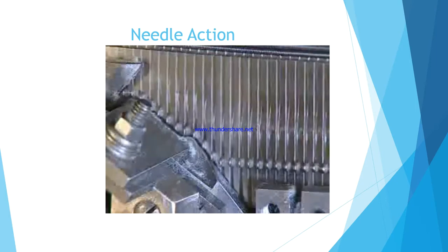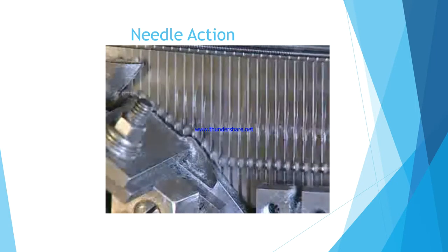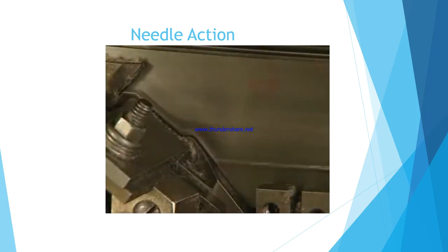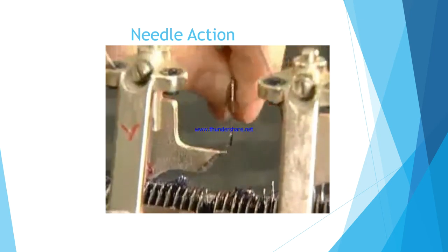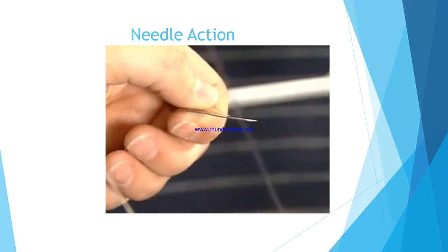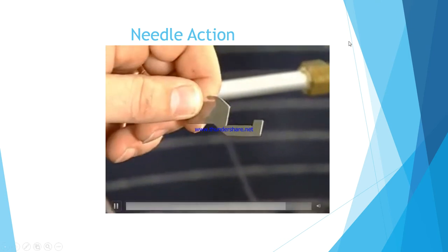And remember that this machine has a cylinder that contains vertical grooves and slots to hold the needles that move. As needle activation occurs, how does the machine control the movement of fabric as it knits? There's one more part, placed between each pair of needles, that you need to see to better understand this. It's called a sinker, and here's what it looks like.